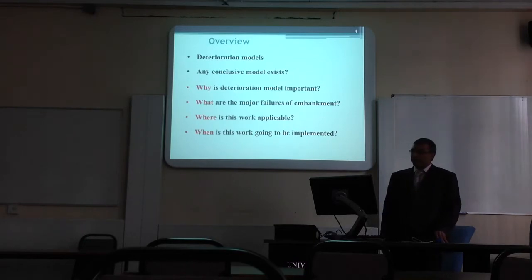So what are the major failures of embankment? The major failures could be bearing capacity failure or slope stability failure, but in the vast majority the slope stability failure occurs, which is mostly shallow failure.